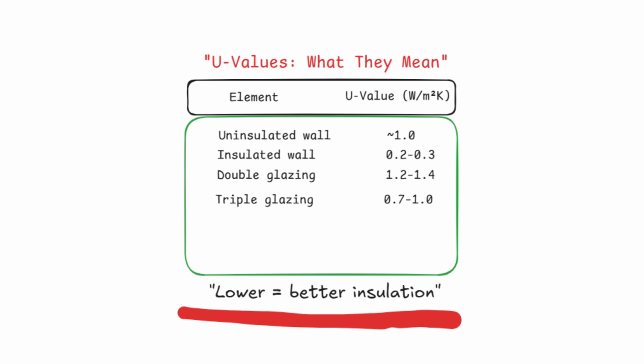Example, a 120 square meter house with average insulation. 120 times 70 equals 8,400 watts, so roughly 8.5 kilowatts of heat loss. That's the heat pump size you need as a starting point. If your installer quotes you a 5 kilowatt unit for that house without doing any further calculation, ask them why. If they quote you a 14 kilowatt unit, ask them the same question. The numbers should be justified by actual inputs, not guesswork.